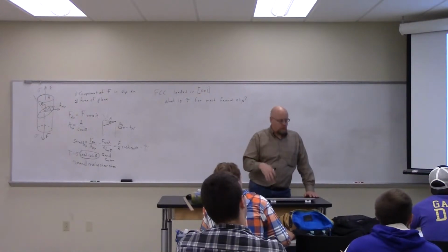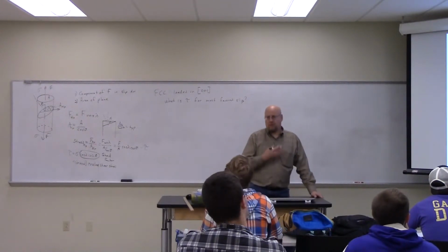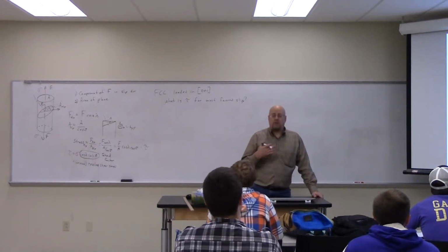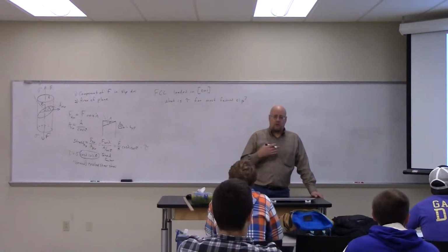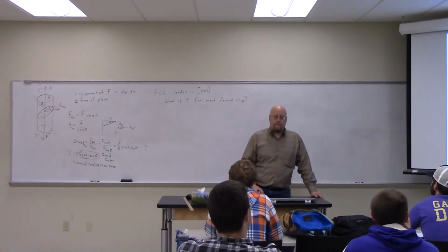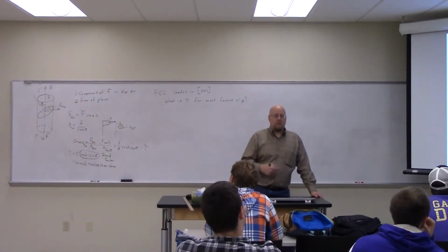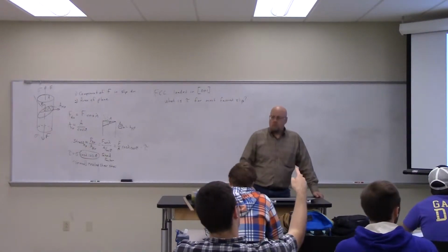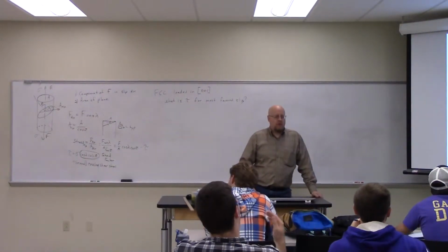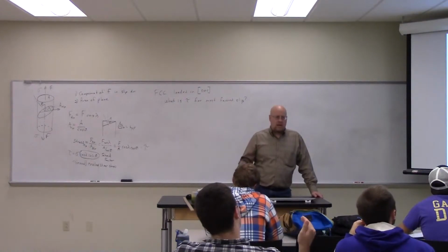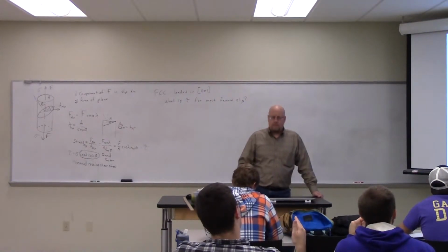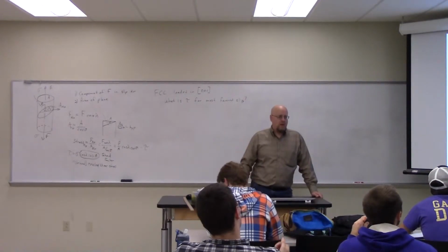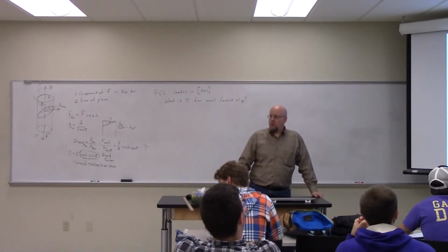First let's just go through and find out which slip system. This may not be the right one. What is the orientation of that plane? If I told you to define that plane, what would it be? It'd be a 1-1-1 plane.